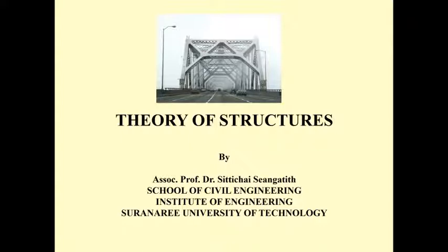And you also may recall that when we analyze the truss, it is assumed to have two assumptions. One, the joints of the truss are frictionless, and second, the loads are applied at the joints of the truss. And you also may recall that the members of the truss can be in compression or in tension only, and that kind of member is called a two-force member.